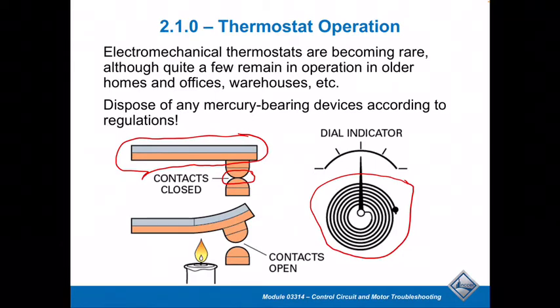An older thermostat would be much more likely to see that issue. So what we oftentimes will see is something that might be a snap-acting thermostat. On some of the thermostats I've seen with the bimetals, all of a sudden they'll get to a point and then snap right into position. So there's very little arcing that occurs in any of those.